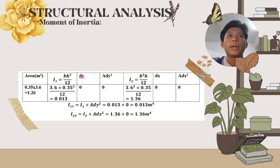In this lab I will explain the structure analysis for moment of inertia by using the parallel axis method. First, we need to find the area of this beam, and then we find the Ix value, using the formula bh to the power of 3 divided by 12, and we get 0.013.